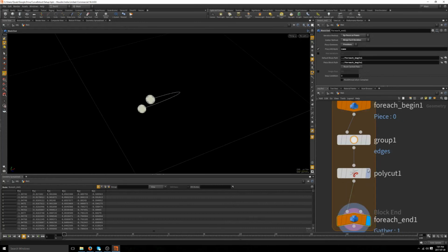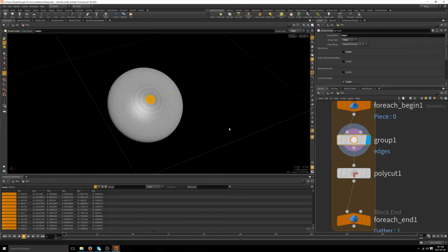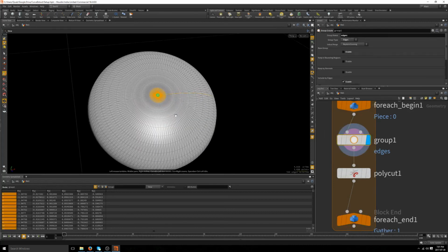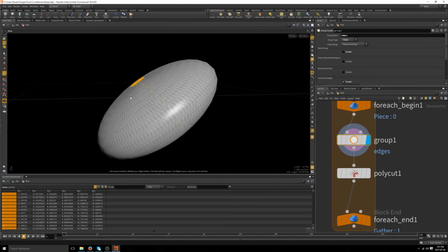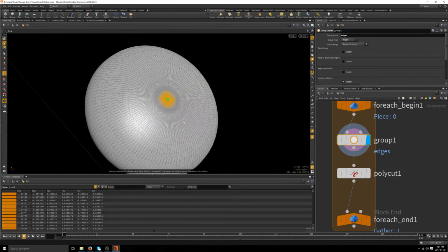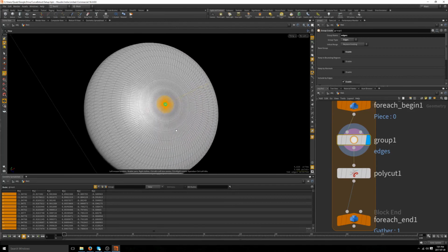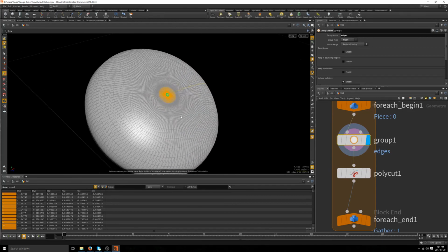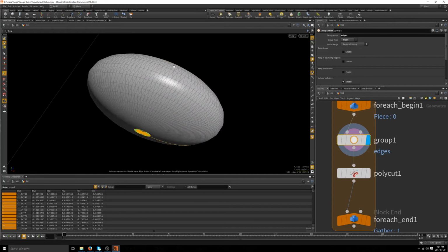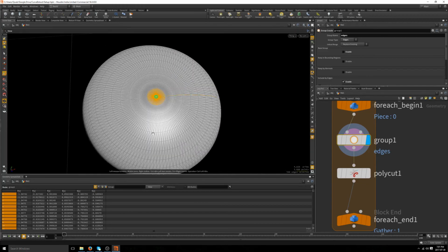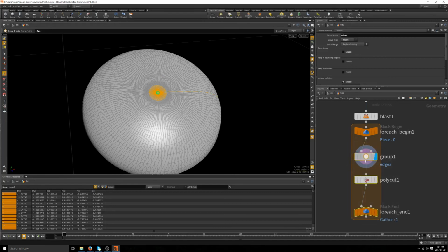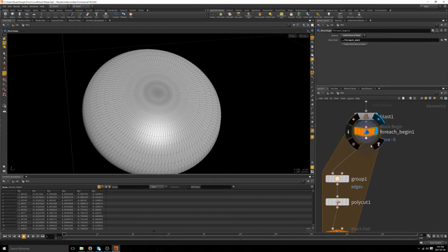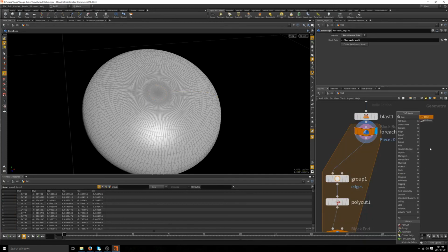So yeah, for some reason poles are not merged when we exported the mesh with Moi. I mean, obviously we didn't want to weld the points, but there is something strange around the poles here. We need to find a way to merge these 2 points, at least all the edges around these 2 points. So for that we're gonna first fuse everything together, every point.